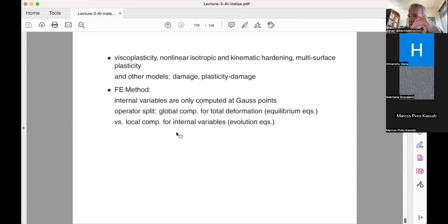You have a similar thing with fatigue failure, because many of these things appear in mechanical and aerospace engineering, since all these airplanes have cracks. It's just the question whether these cracks are stable or not. Taking linear fracture mechanics to judge the stability of the crack is certainly not serious enough, because it depends on the history of the plane, how long it has been flying, how long it has been through these tough conditions, and so on. So one really has to be able to observe this at a very fine scale and take this into account.